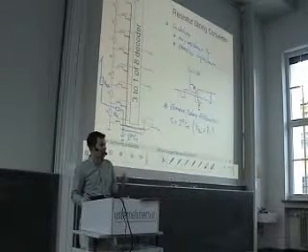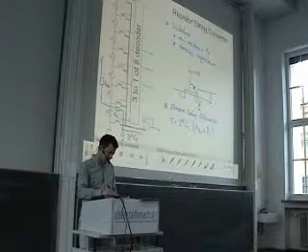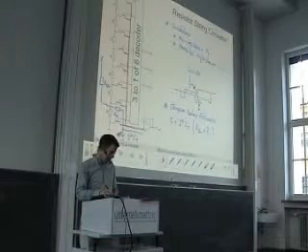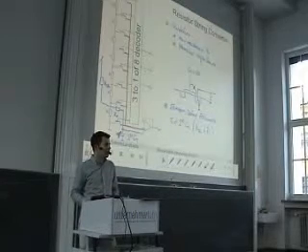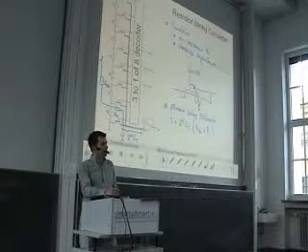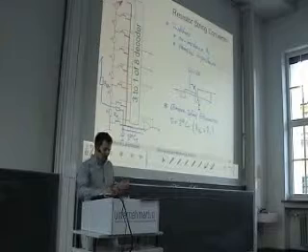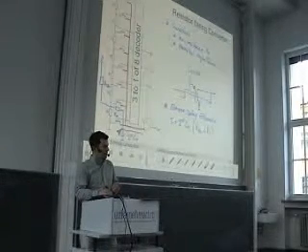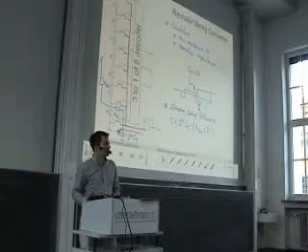Okay, so if we apply the reference voltage, then the voltage divider starts working and charges up all these intermediate caps, so I neglected this. But this cap, of course, is the one where you always have to change the charge if you toggle these switches. So if you change the input of your DAC, you turn on another switch, so you have to change the charge on this cap, and this requires a settling time that can be estimated by this Elmore delay.